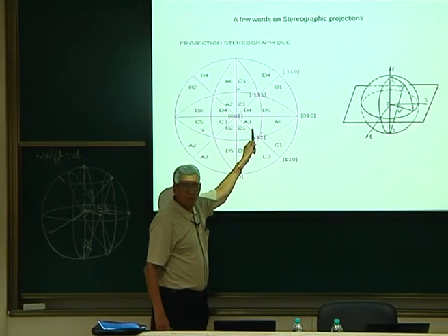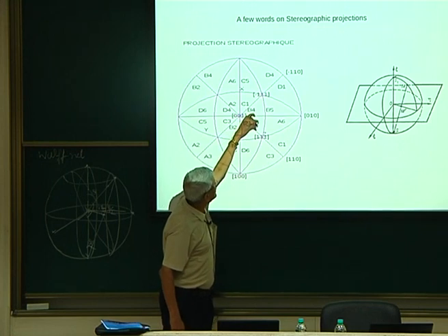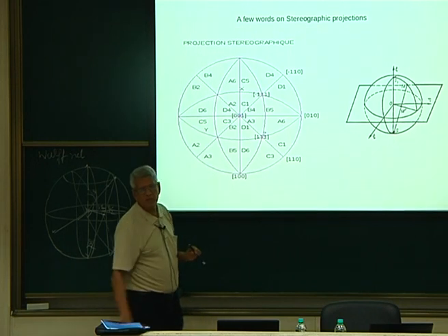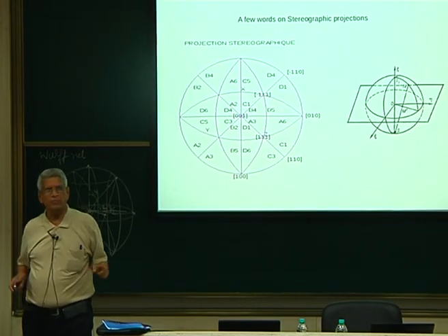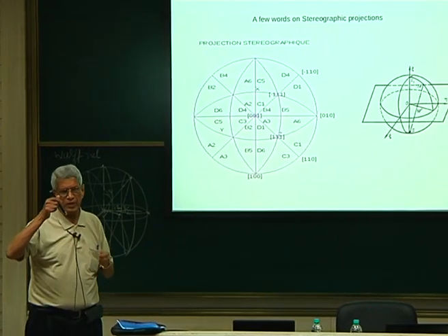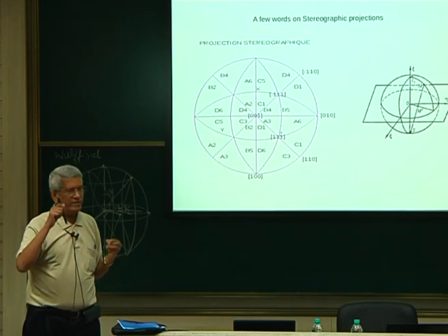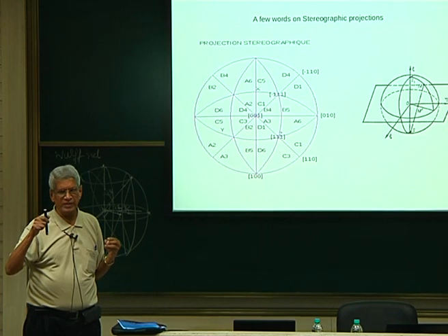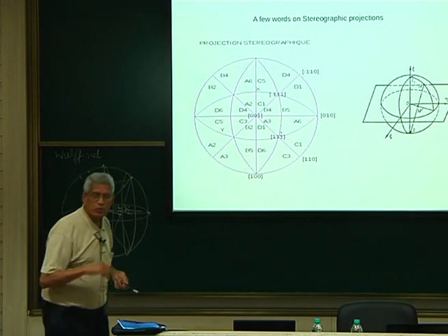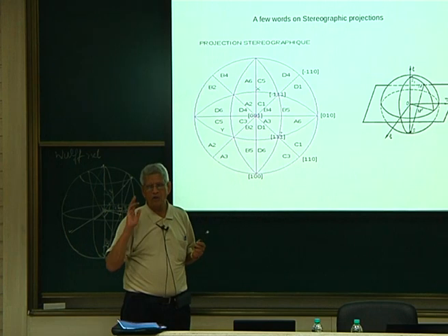Now, suppose we want to find out, suppose we choose an orientation of the crystal which is going to be here. Okay. Then what is the slip system which will be activated? You know, from Schmid's law, 2 angles are going to be there. One is the angle which the orientation makes with respect to the slip plane, and the other is the angle which it makes with respect to the Burgers vector. The product of that is what we call the Schmid factor, correct? So it is maximum when both are going to be 45 degree or close to 45 degree, correct?